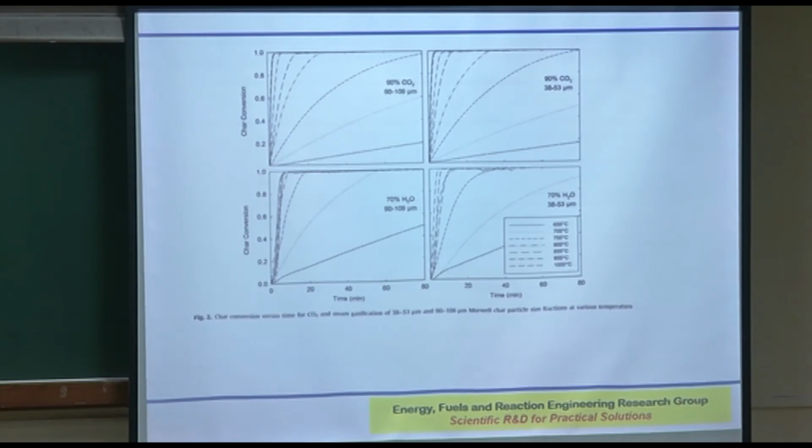Temperature wise, no, we wouldn't try to get hold of a time from here that will correspond to the entrained flow gasifier's time. Entrained flow gasifiers will be limited to about 7-8 seconds anyway. That's what the gasifier manufacturers will give you. So here your only comparison is by what ratio the conversion rate increases as you increase the temperature from 600 to 900.